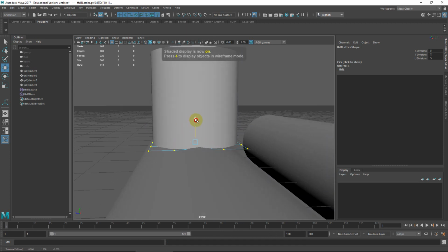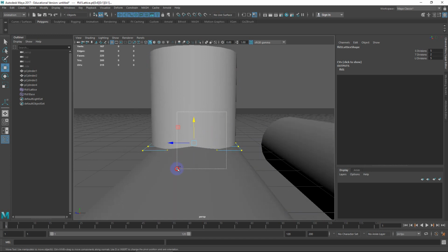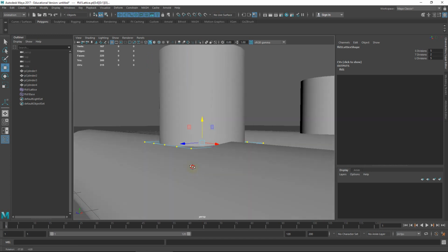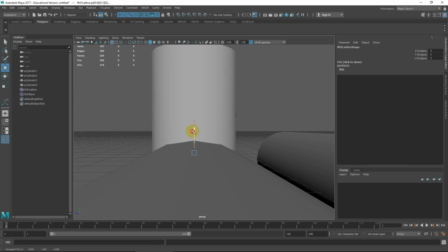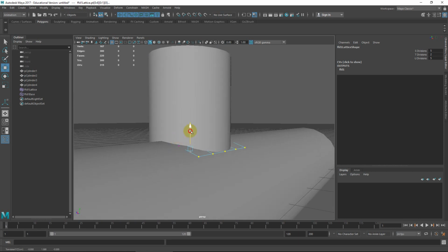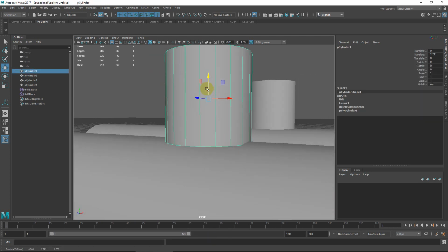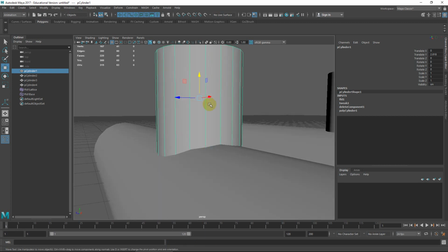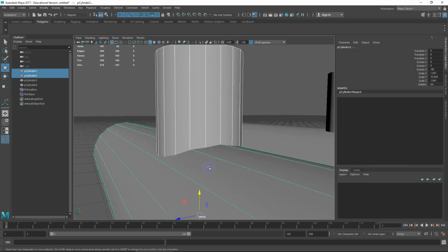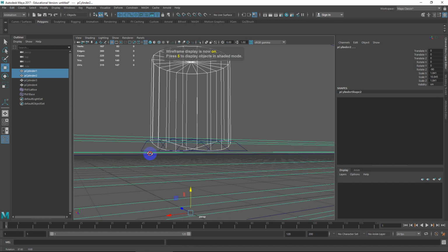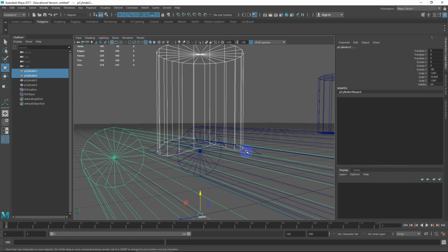So what I'll do is pull down until I get some sort of contact with the surface. Control, click and drag to deselect, and then I can pull down the outer edges. Now I get fairly good contact between the two surfaces. We just lift this up. Let's take a look at both of these. Hit F4. So one piece of pipe is sitting pretty cleanly across the other.